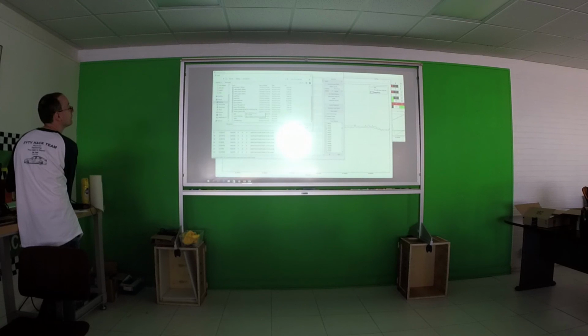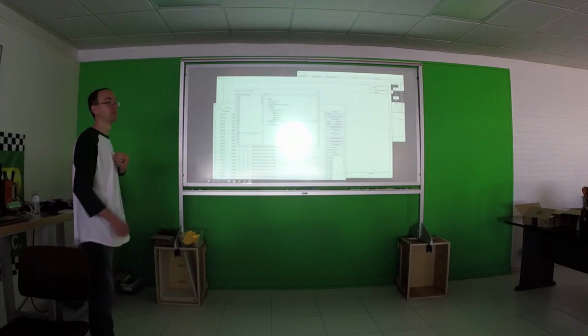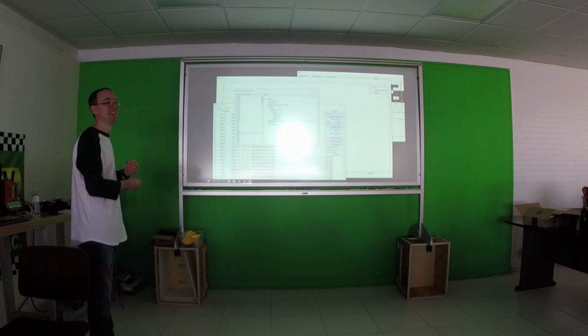UQM publishes their CAN data if you buy the motor from them. Yeah, except that we ran a Coda, and it didn't use the UQM scheme. They had a whole different software thing. They had their proprietary DCM. So we had to reverse engineer the whole control of the UQM inverter. And one of the problems was in the message that carried the real torque command, it had this byte at the end of it, a CRC byte of some sort. The bite me byte. Collin cracked it.